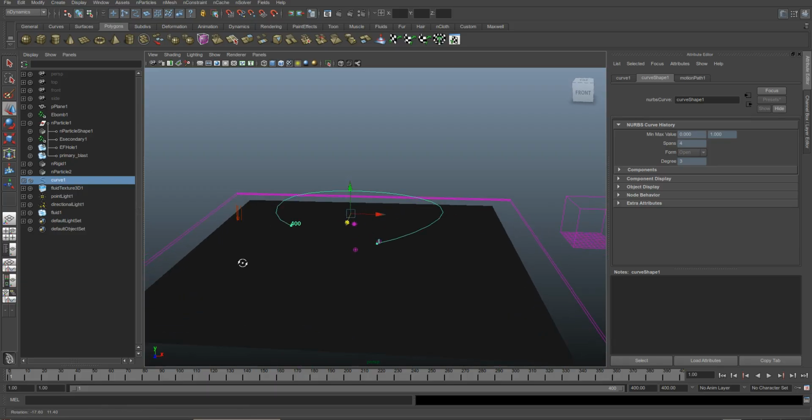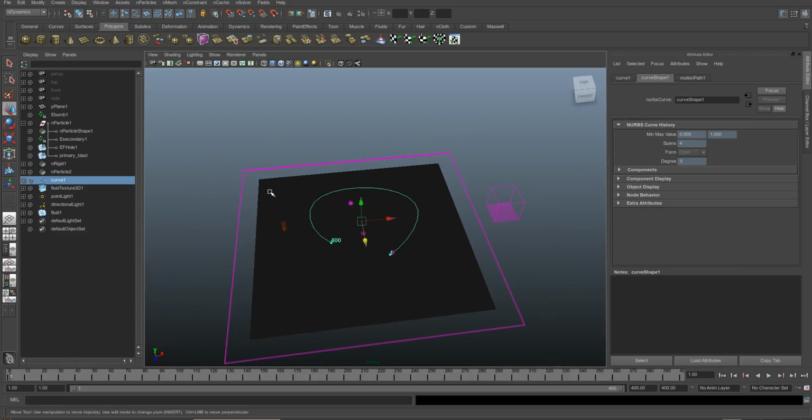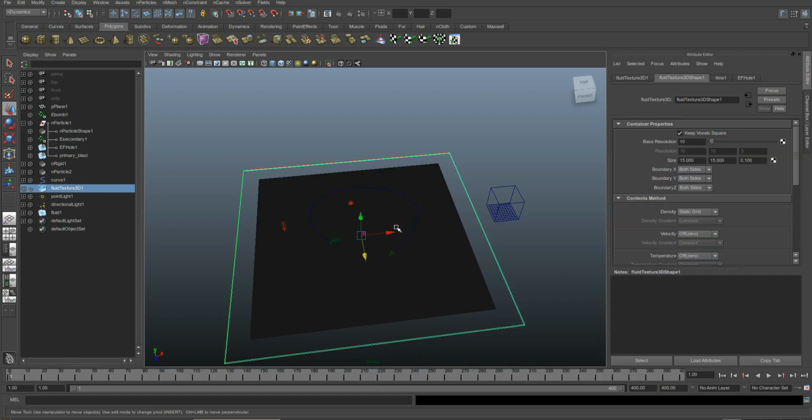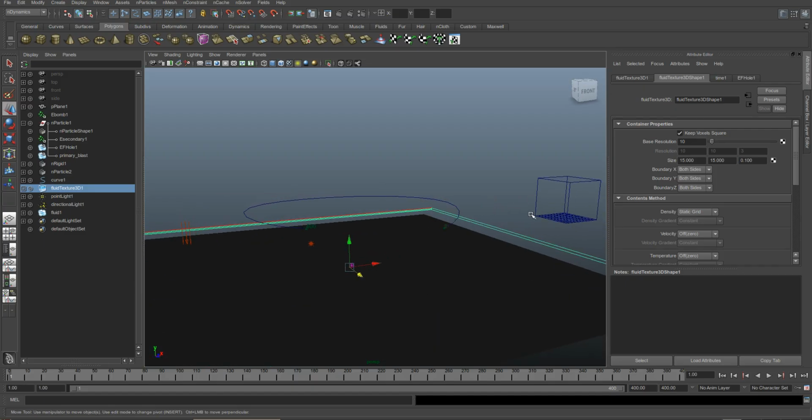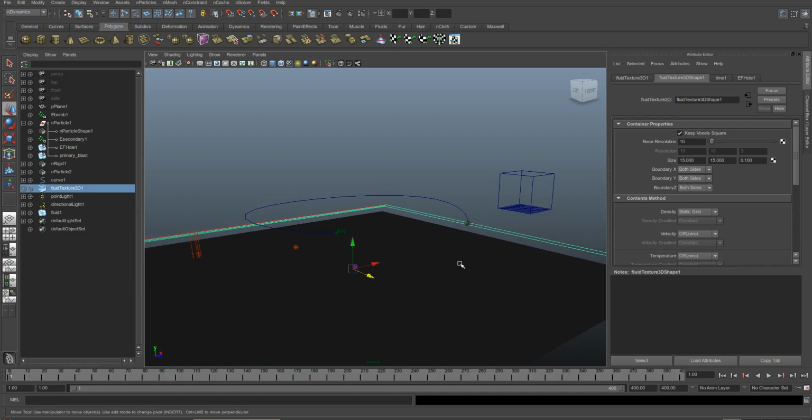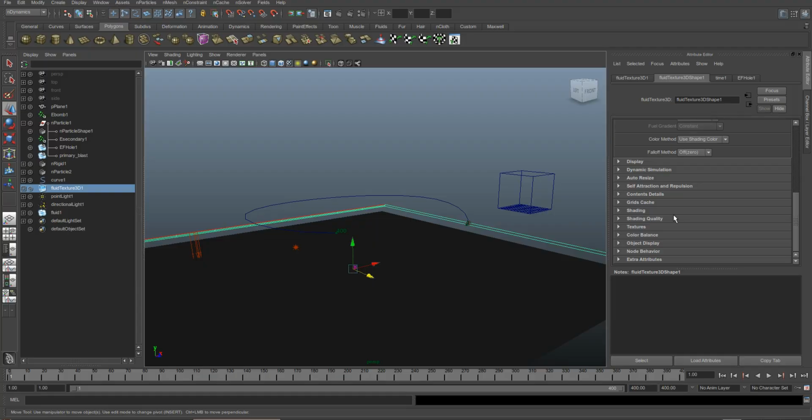The only limitation you have is the size of this ground plane and the size of this 3D fluid texture node, but they can easily be resized. So using auto-resize allows you a little freedom. It's also much faster for something like this, so it's something to bear in mind when you're designing your next fluid simulations. If you can use auto-resize, you should probably try to incorporate that in your workflow. Anyway, just a small quick lecture there.